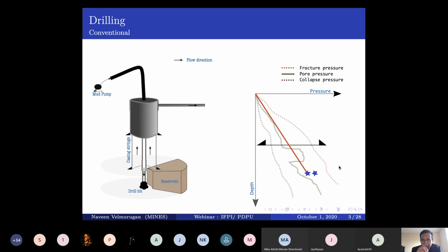And in conventional drilling, the only degree of freedom that we have is to change the density of the drilling mud and then start circulating from the top. If you do that, you can see that the pressure profile takes a linear shape and is still given by this gradient. There could always be some section of the open reservoir where you are not able to manage the drawdown, and you will still have some influx from this region. This is a drawback in conventional drilling.